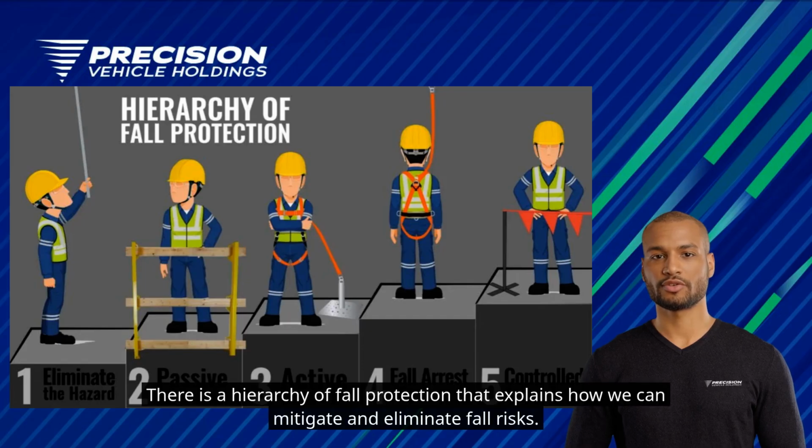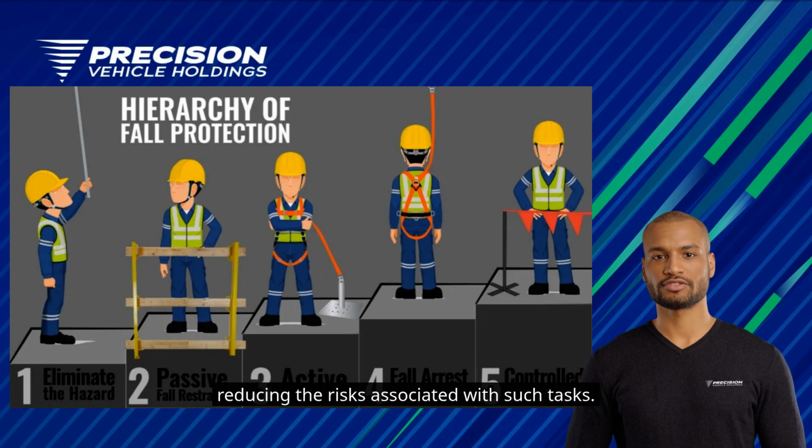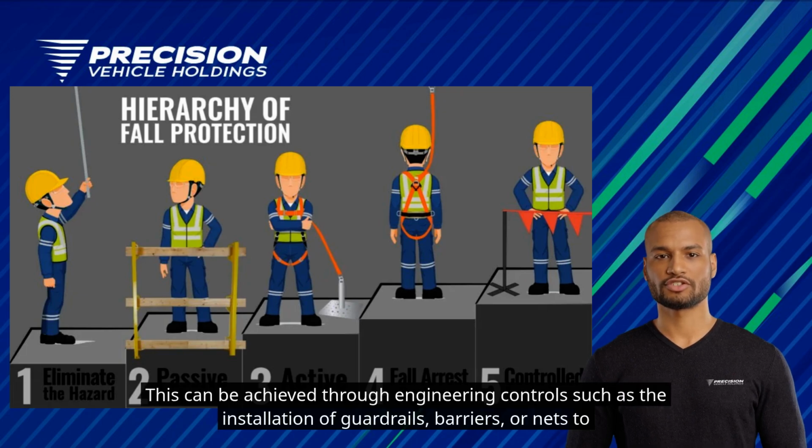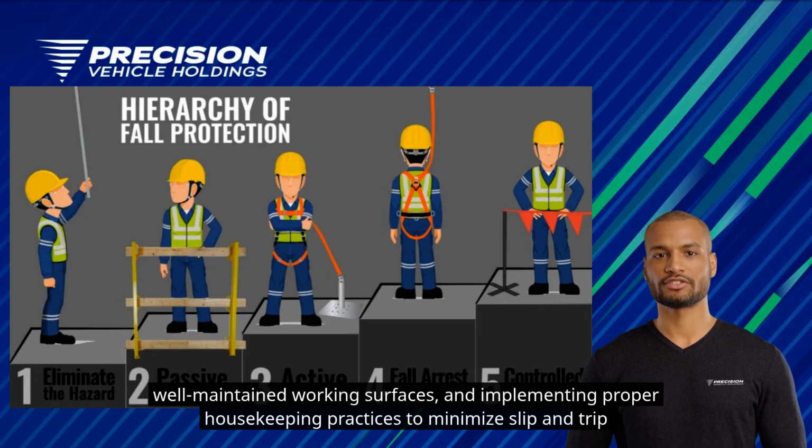There is a hierarchy of fall protection that explains how we can mitigate and eliminate fall risks. Elimination and prevention measures involve eliminating the need for workers to perform tasks at heights or reducing the risks associated with such tasks. This can be achieved through engineering controls such as the installation of guardrails, barriers, or nets to prevent falls. Other prevention measures include using aerial lifts or platforms instead of ladders, providing stable and well-maintained working surfaces, and implementing proper housekeeping practices to minimize slip and trip hazards.